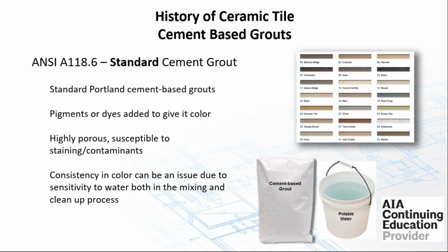So what we end up having is that all this extra water getting into the grout, we start washing out the color, we start fading the grout. And oftentimes, if you're on the job site, look at the wash water that they're throwing away, and you'll see that the color of your grout is going down the drain or out into the ground. So often as the design team, you've specified a mocha colored grout and you come back and find out it looks like latte because the color has been washed away by the use of too much water, both in the mixing and in the cleanup of the grout. And this can be a problem with the Portland cement type grouts.